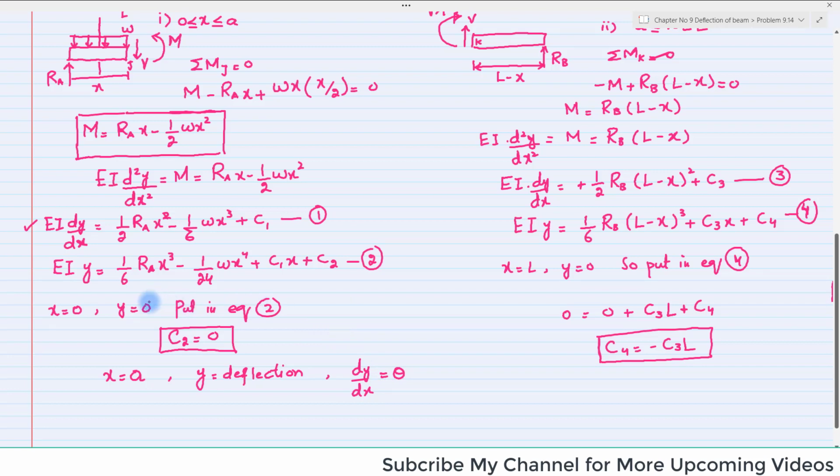So you can see you will have equation 2 as well as 4 and 1 as well as 3. So equations 1 and 3 are for slope, while 2 and 4 are for deflection. Clear? So you will have to put x is equal to a in equation 1 and equation number 3, and you will equate them, because you can see the left hand side of equations 1 and 3 are the same. So you can equate them and put x is equal to a.